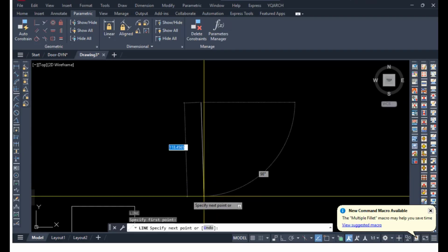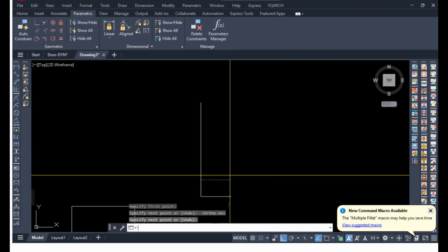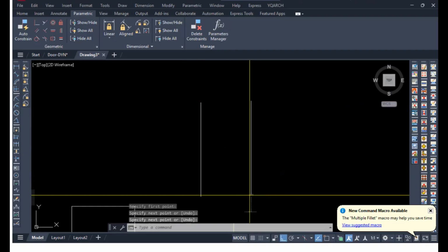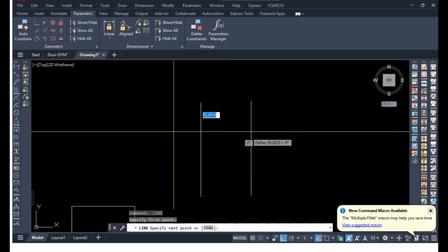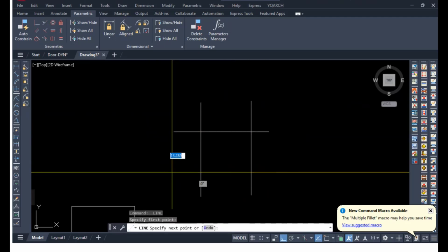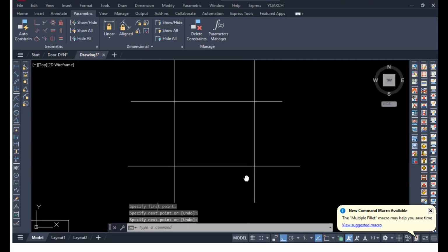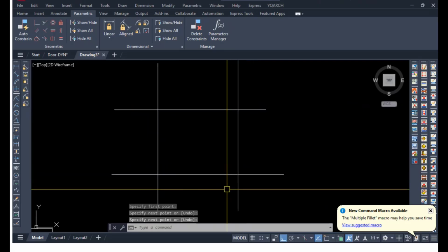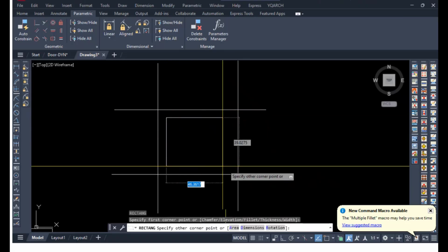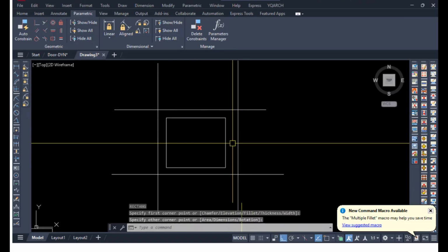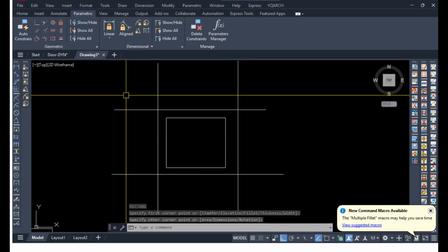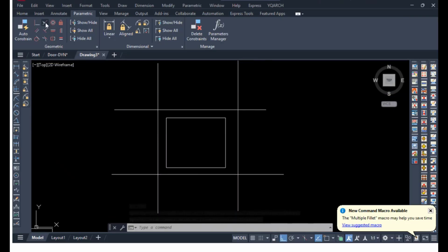So for the work that you do all the time, when you're doing the grid line or the wall, you make the grid line, and you need the wall to attach to the grid, right? How can you do it? You do this by applying the collinear.